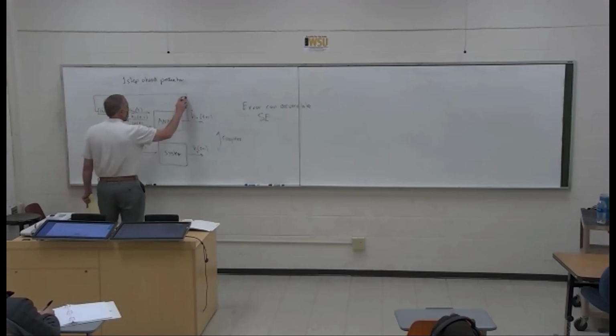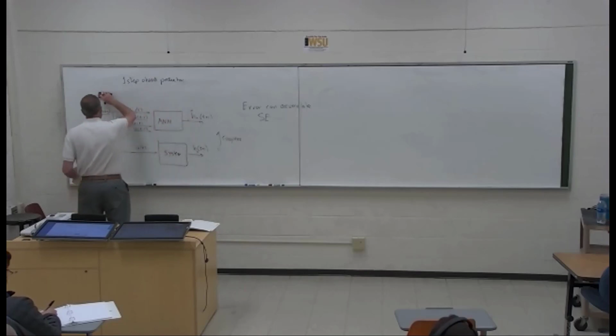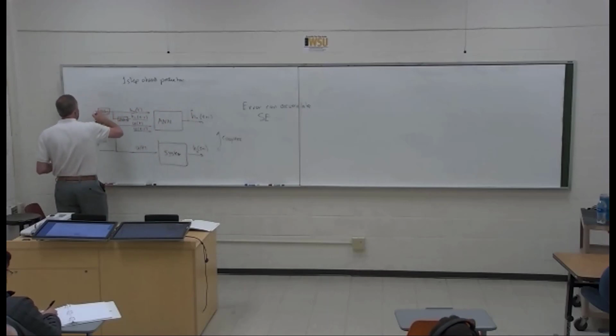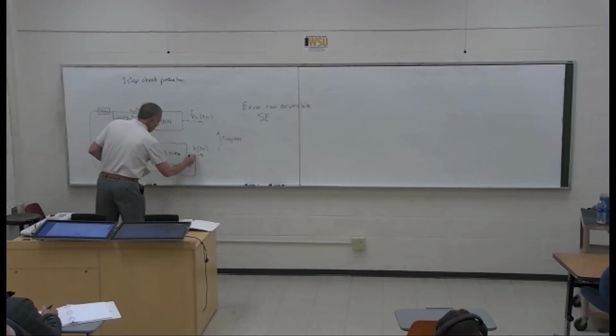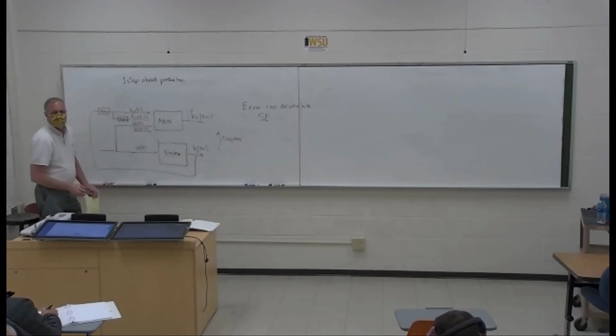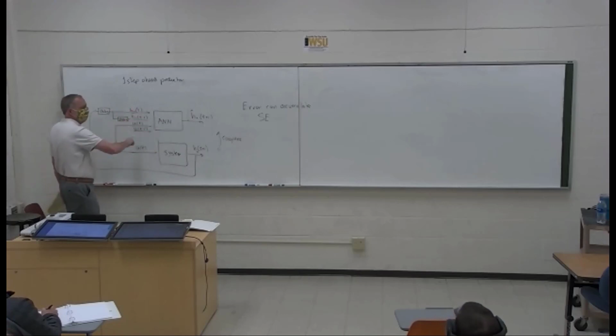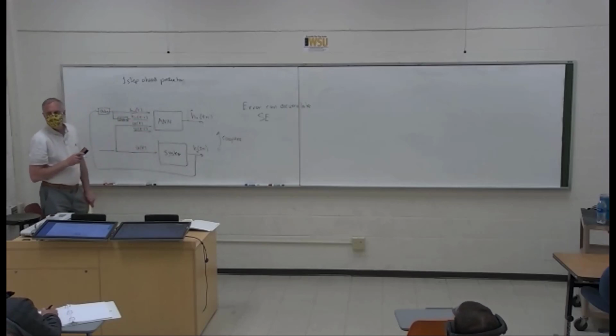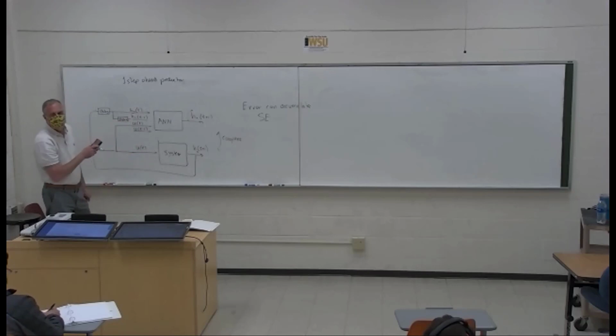And so what changes there is where this feedback signal comes from. Instead of coming from the model, since you're running the system, you get it from the actual system. So you have a sensor on board the system. And essentially that resets the data to what the system is actually doing. And so you can see the error would not accumulate then.